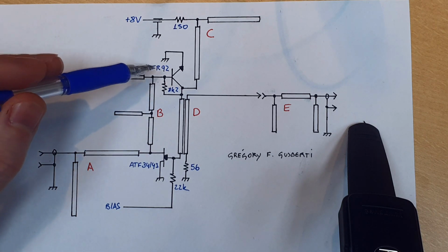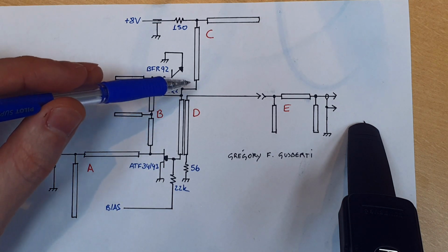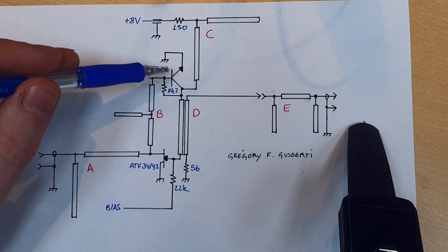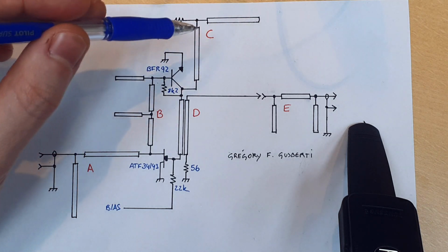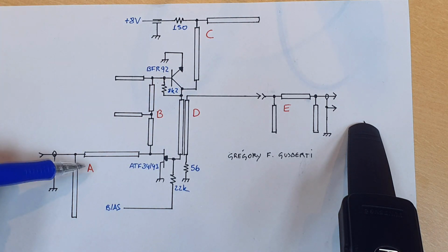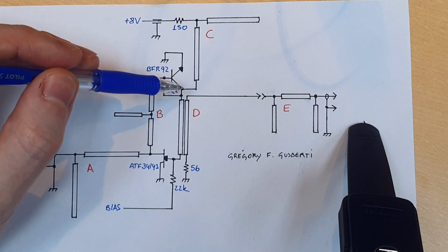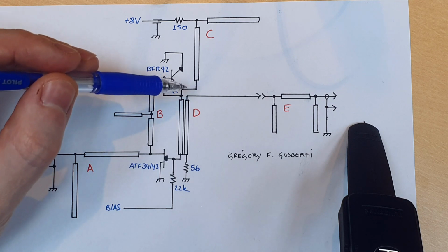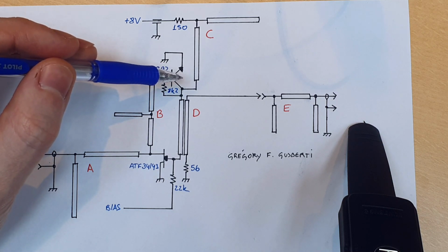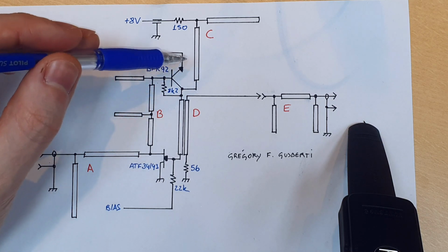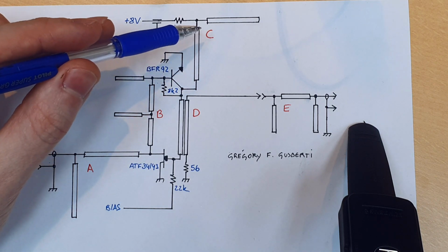So here we have the 800 MHz because the 800 MHz can pass through the network and the signal is amplified by this common emitter amplifier here. The common emitter is biased by the same network here, the C network that we saw here at the input. This network is used to bias the transistor and to maximize the gain of the amplifier right at 800 MHz. So this transistor is operating as a class A tuned amplifier. The peak gain at the right frequency is given by the biasing network here, also made by transmission line transformer.